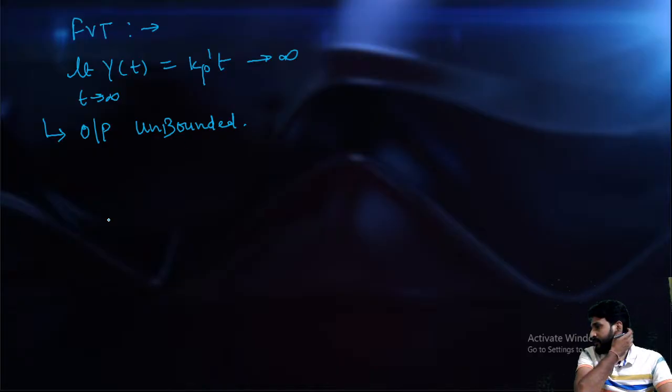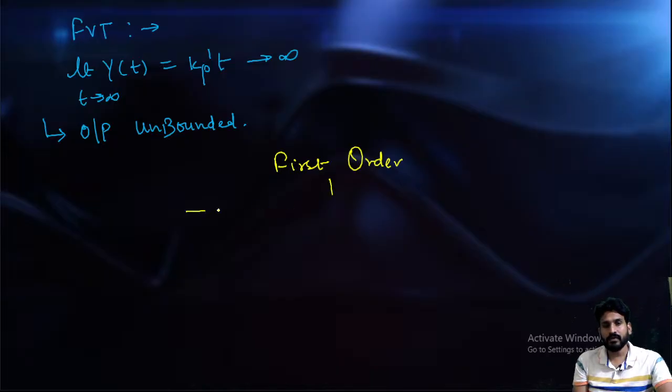Okay, so if you see here, till the 5 examples the case is different. I'm getting G = Kp divided by tau ps plus 1. In tau p, I can see both terms, capacitance and resistance. All those 5 examples are related to the first order, and for the first order, the response to step input is bounded. We already checked that. But the unit step response for the pure capacitive system is unbounded, though it is still first order. Then I can conclude that there are two types of first order system.